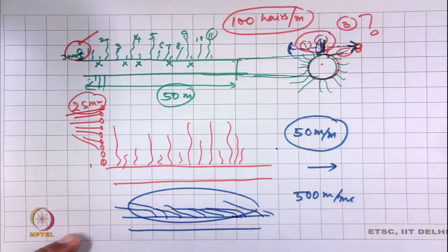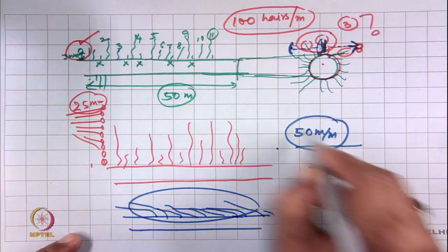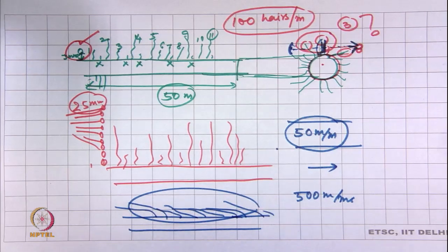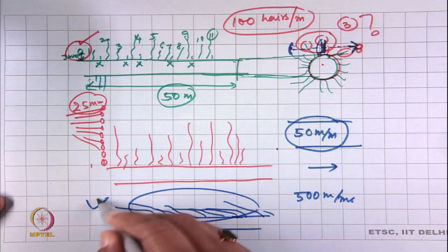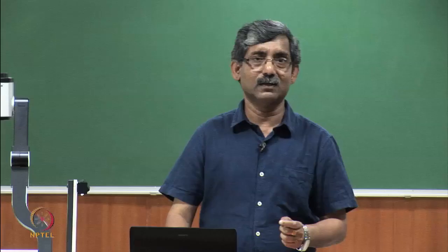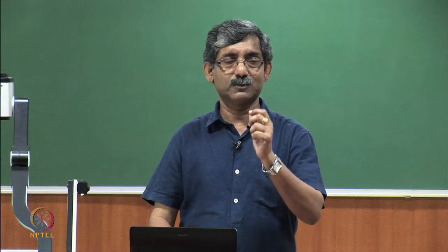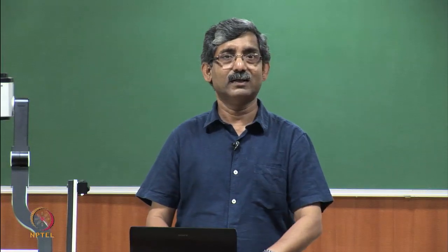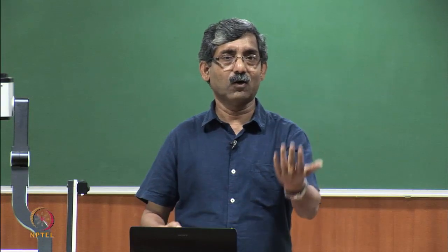That is why the speed in this instrument is specified. If we change the speed, the total hairiness reading will be different for the same yarn. So it is recommended that we must run the yarn at a specified speed.